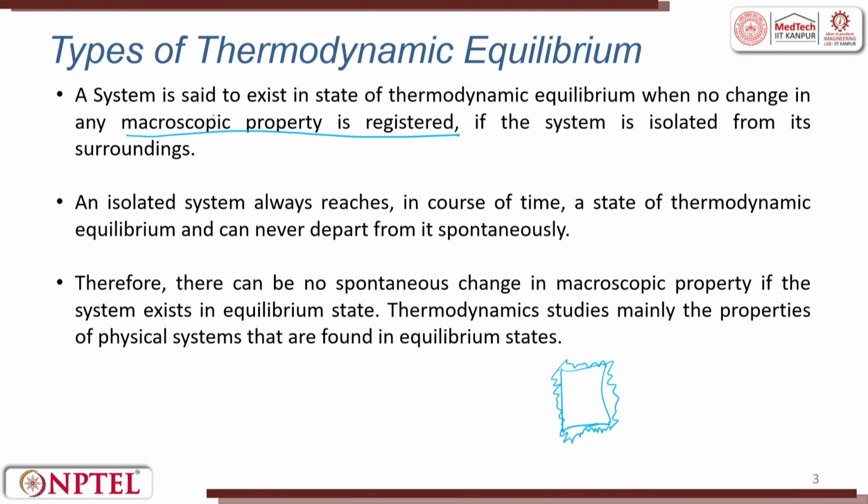A system is said to exist in state of thermodynamic equilibrium when there is no change in any macroscopic property, pressure, volume, temperature, if the system is isolated from the surrounding. If you seal it, nothing is going to happen. An isolated system always reaches in course of time a state of thermodynamic equilibrium and never departs from it spontaneously. It slowly moves out of its existing state. So, that is what happens in your thermoflask also, right. An isolated system always reaches in course of time a state of thermodynamic equilibrium and never departs from it spontaneously.